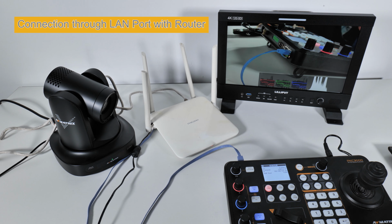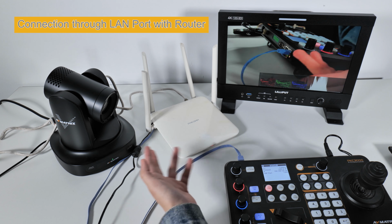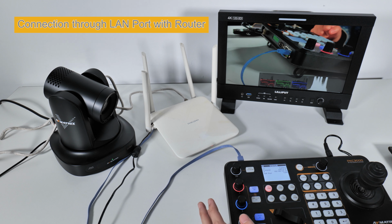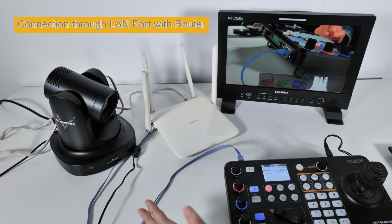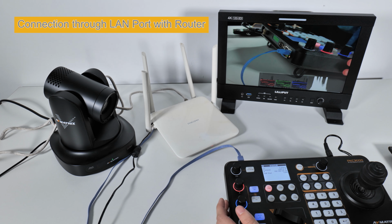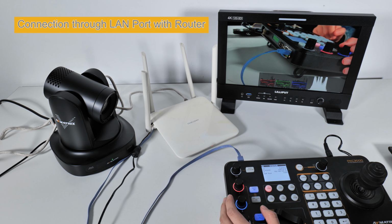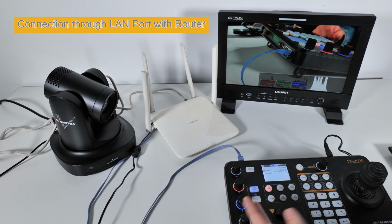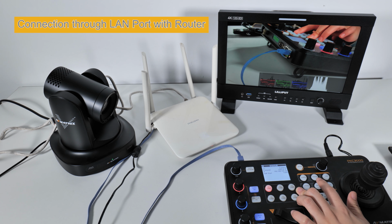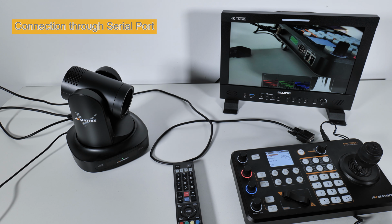The second method is connection through LAN port with the router. It is similar to the connection through network cable. We should make sure the PTZ camera and PTZ controller are in the same network subnet, and then after setting the IP address of the PKC3000, we can search for the PTZ camera by pressing the search button or the inquire button.